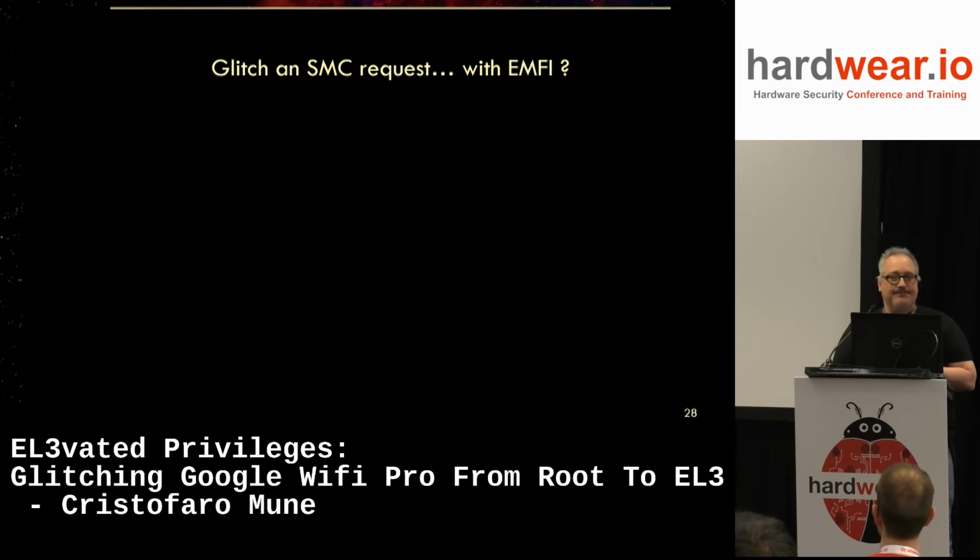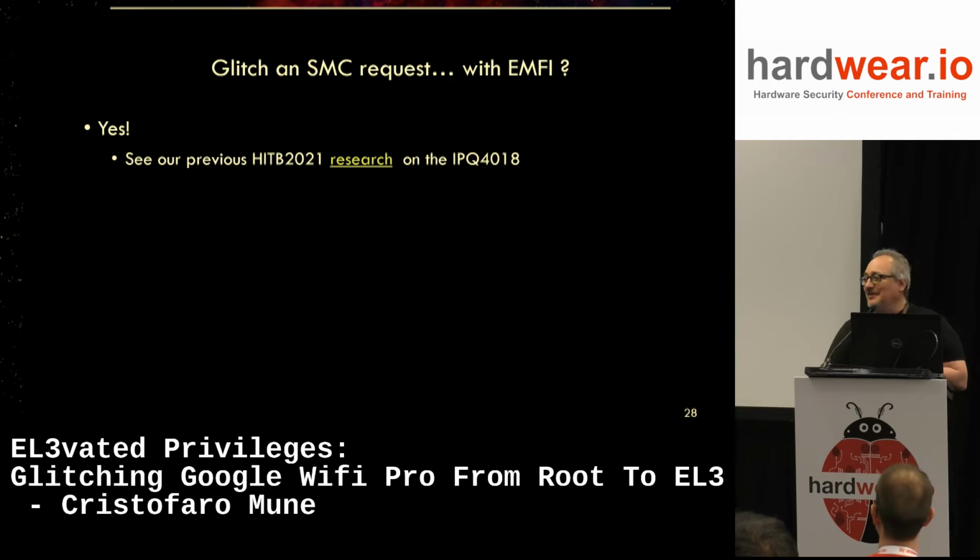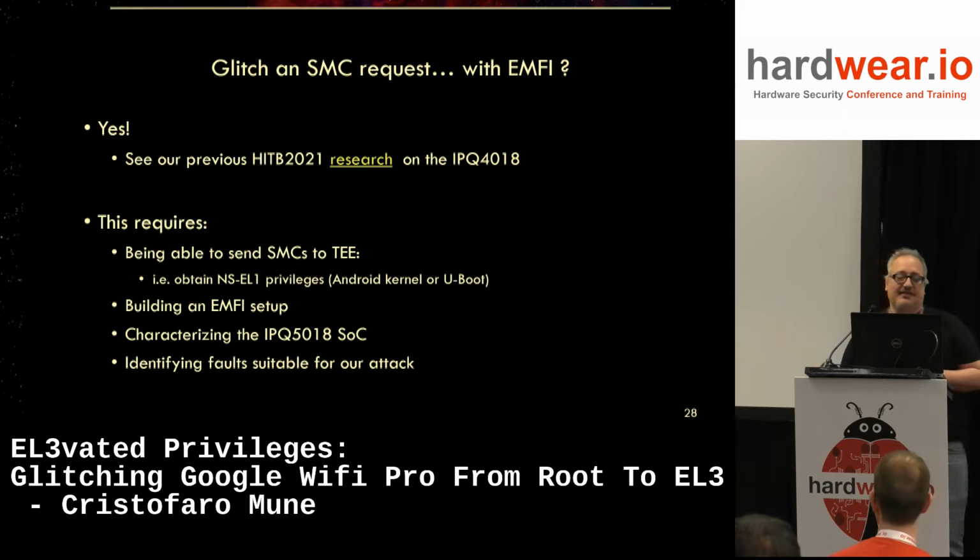So glitching an SMC request with EMFI, is that even possible? What do you think? Well, we did it already in 2021 in our research on the IPQ4018. It was already done, but for a really different purpose in that case. Now we are building a more structured attack. This requires that you are able to send SMCs to the TEE.